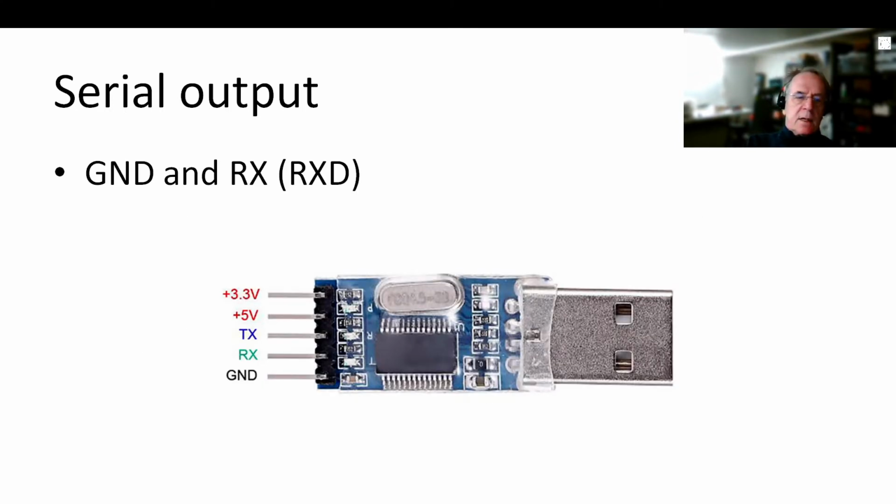What do they look like? They look like this. I've connected in the ground, this pin here, and I've also connected in the receive. So my TX on my PIC is connected to the RX on here. You're quite safe to connect them. Just connect these two up. In actual fact, I should be using the term TX1 just to make it very clear. It's transmit because there's more than one USART channel in this PIC.